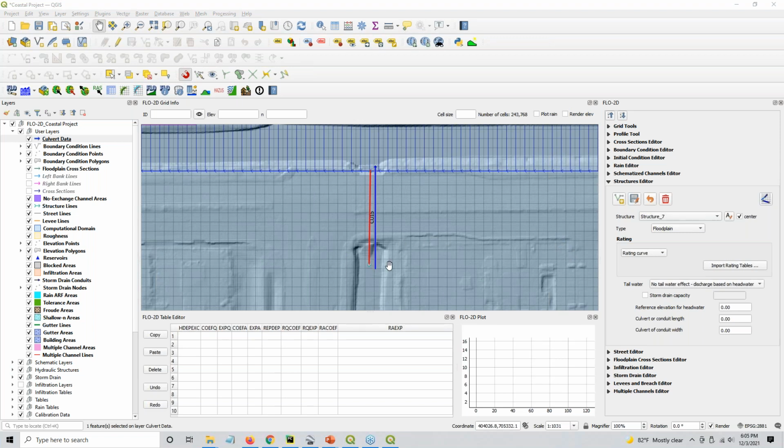Okay. I'm back at the one that's slightly different. So I'm going to go ahead and show you this one. So this one is CU15. So CU15 and floodplain to channel rating culvert equation. And CU15 has 168 for the length, and the diameter or the height is 6.